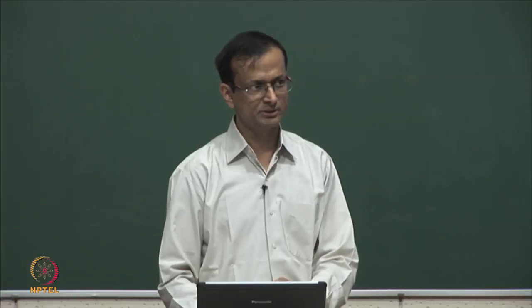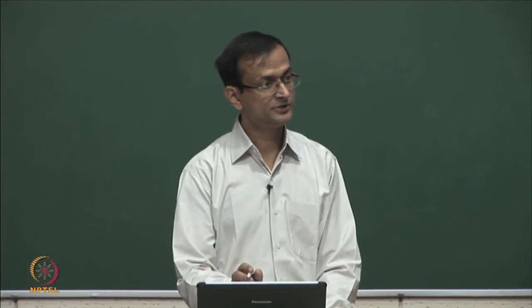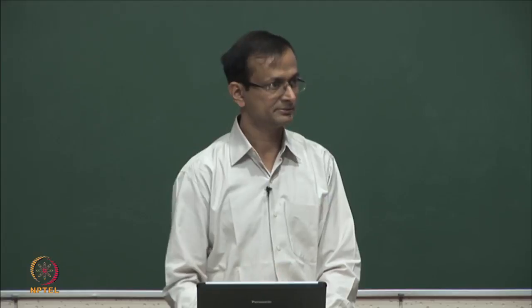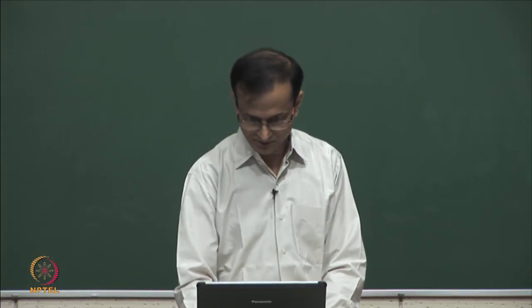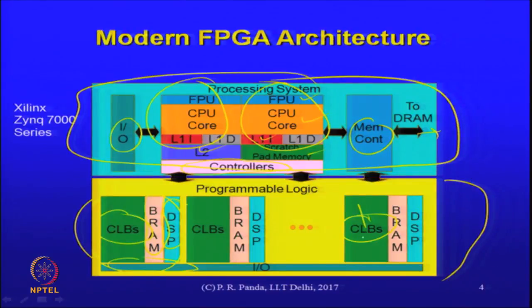Yes. Also, that is one part of the FPGA's memory, which is the configuration memory. This memory is not visible to the programmer, to the designer. In our picture, the block RAM is what is available to us for storing and retrieving data. The block RAM structure we can control. The configuration memory I did not really show in this picture. It has to be embedded as part of the CLBs somewhere, but we do not get to see that.